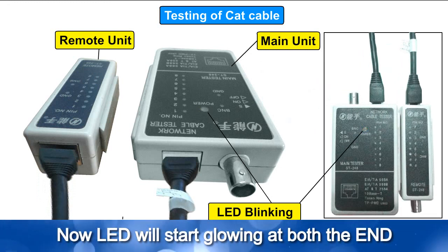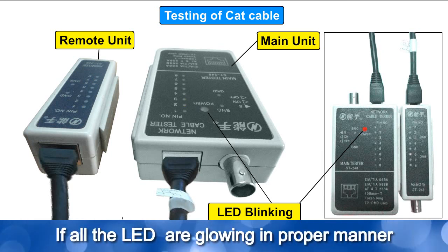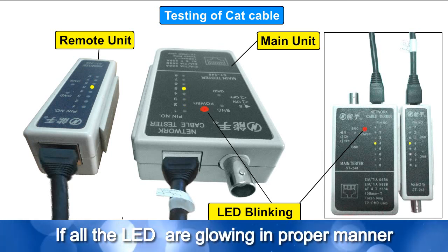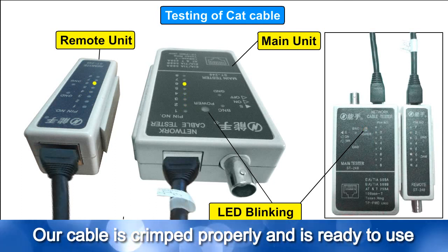Now the LED will start glowing at both ends. If all the LEDs are glowing in a proper manner, our cable is crimped properly and is ready to use.